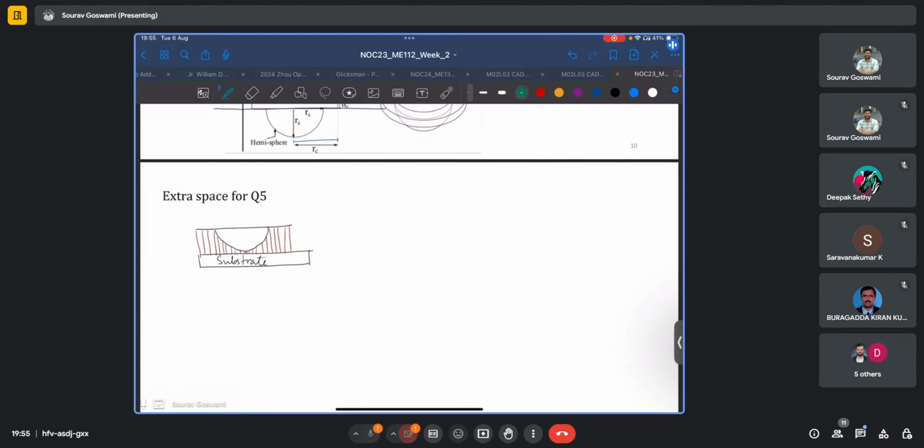But as we already saw, the support in this region will be stale because we will be generating this support from the very first slice itself, but it will not be immediately useful. And the actual overhanging part that the support is being built for will only be encountered at the very end near the equator. Similar for this side.